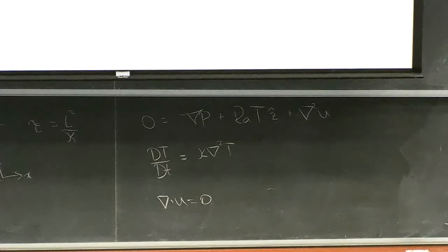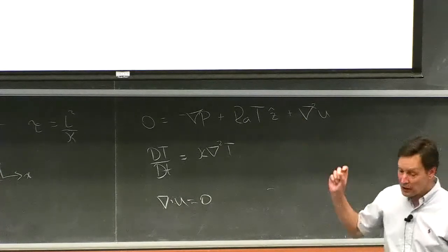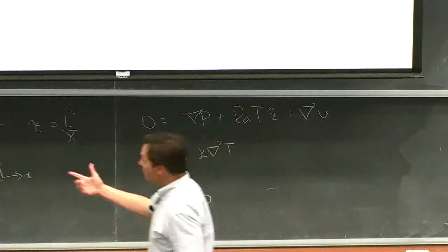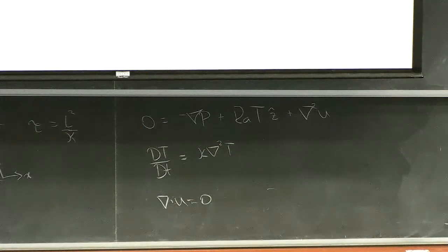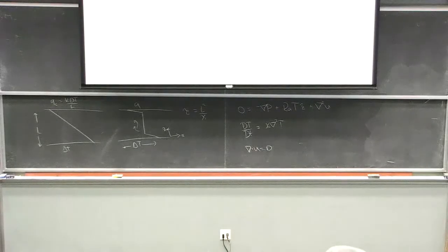And so the reason why non-dimensional equations are really, really powerful is that by making a few simple assumptions about how the system works, you can completely characterize it based on what are the dimensionless numbers that appear in your equations. So for example, in this process, you can imagine what's happening here at the top, right? You're getting cold fluid that's forming at the top. It gets cold, the layer thickens as it conductively cools. It gets unstable and it drips off, okay?